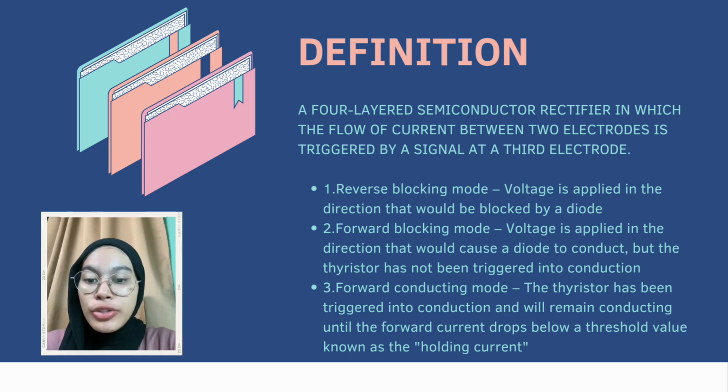Thyristors are mainly used where high currents and voltages are involved and are often used to control alternating currents, where the change of polarity of the current causes the device to switch off automatically, referred to as zero-cross operation.